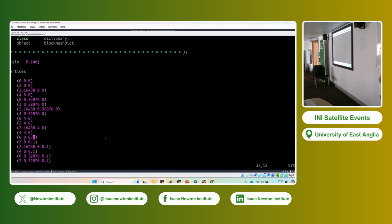What OpenFOAM will do will be to set alpha.water equal to 1 to all the cells inside this box. So along Z, this box can be infinitely long as it's thicker than the domain. We need to give a fixed domain size along Z, and it doesn't really matter which value you give.